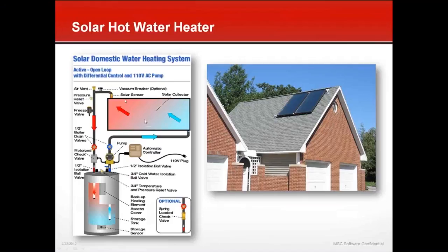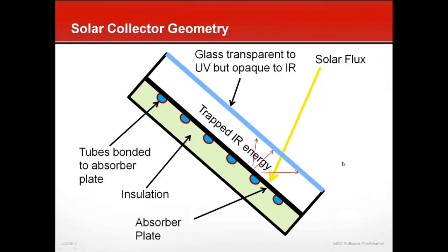And you can have a parallel passageway, which most collectors use. I chose to do a serpentine pattern that goes back and forth just to make a more interesting pattern on the absorber plate. But traditionally, we would use a header on both ends and parallel flow through there to be a little more efficient. Here's basically the things that are involved with a solar collector.